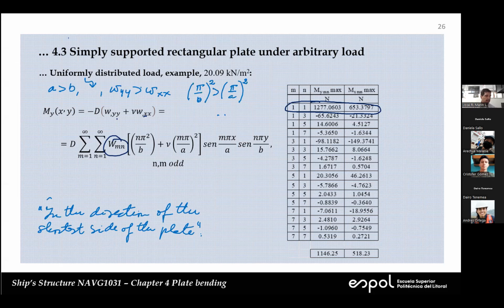That depends usually on the type of loading, but in general, you look in that direction. Just a good practice is to evaluate both, okay, in X and Y. But from the very beginning, you know that probably the largest stresses will be sigma Y in our reference system. It's always a good idea to evaluate both. But if you are short of time, go directly to sigma Y.